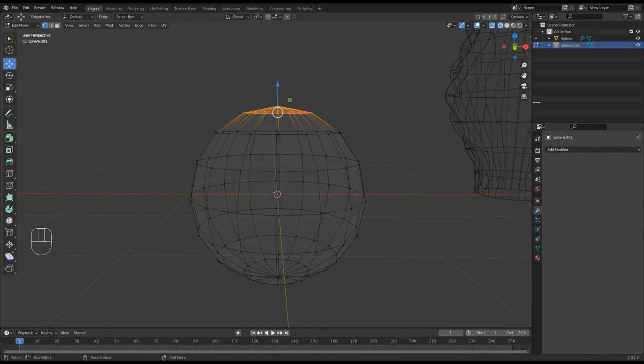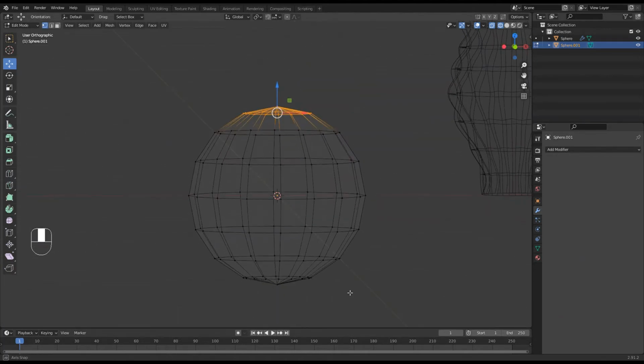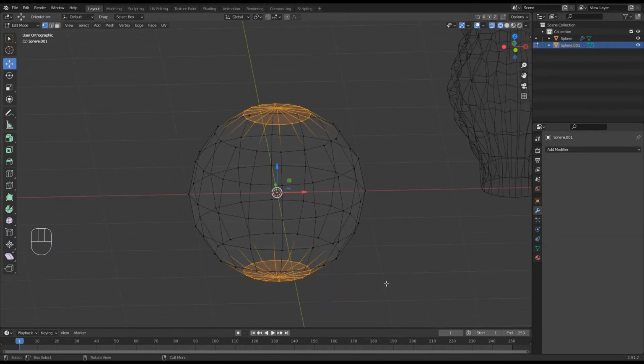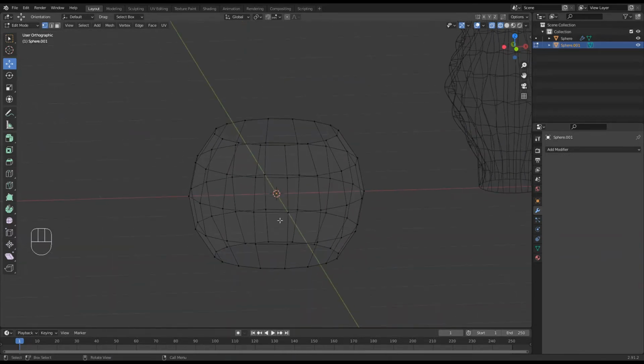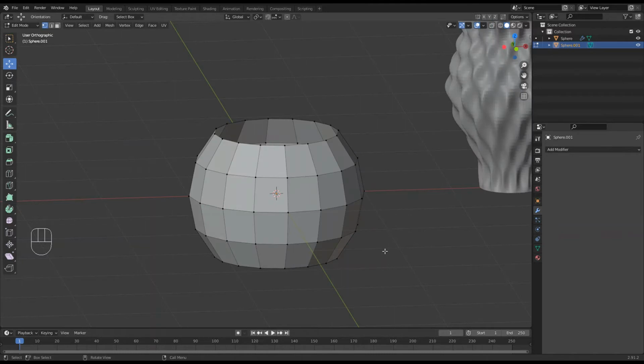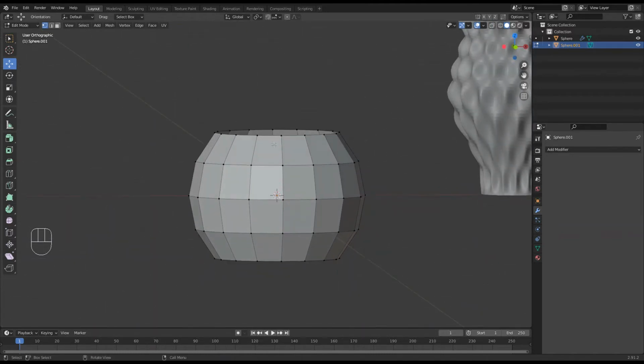And it's a case where orthographic view is better, that it's more just straight on. And so that's selected right through. X to delete the vertices, so that's better. Now I want to go back to solid view, so I press the Z key, this wheel comes up and I just click on the solid. Okay, now what I want to do, just expand this one up a bit